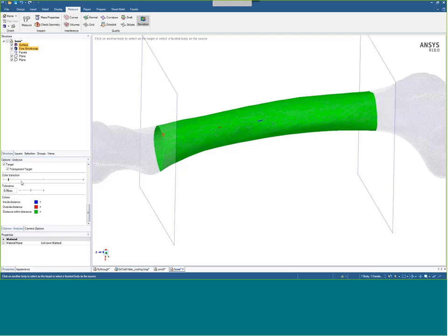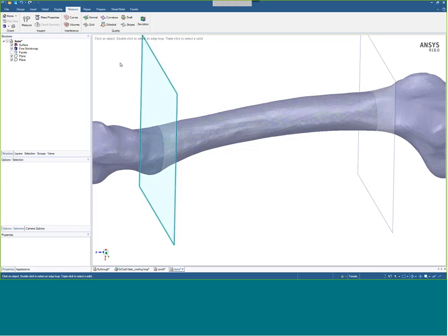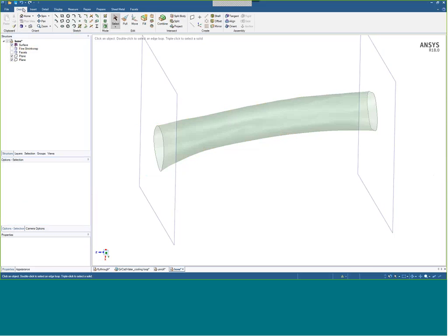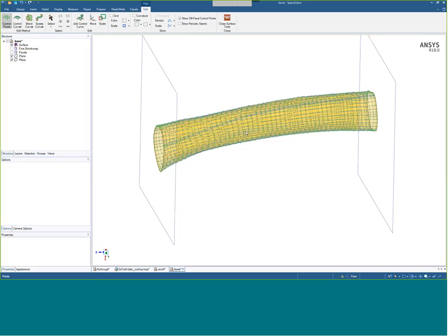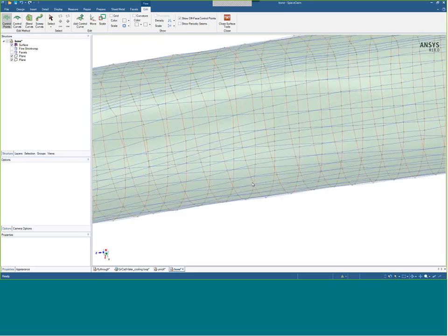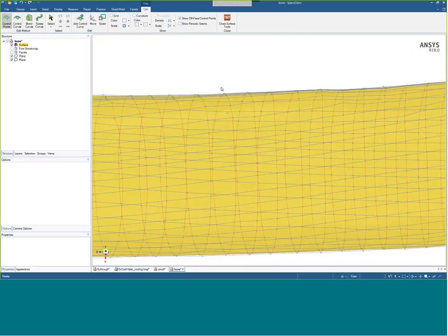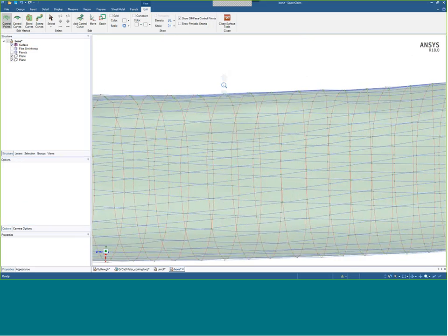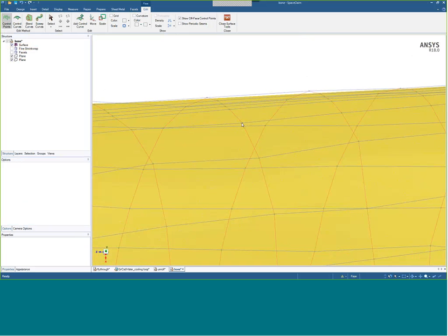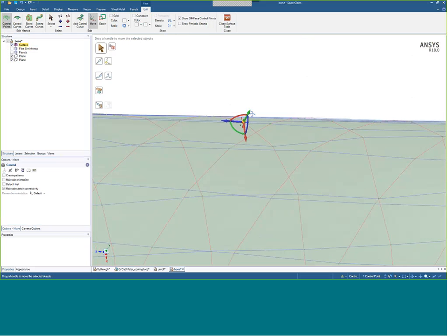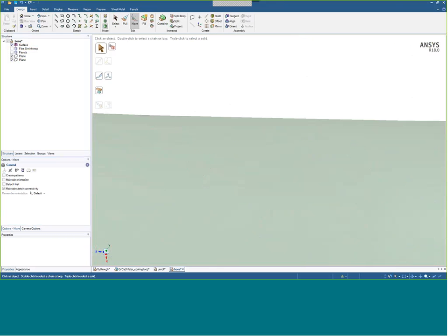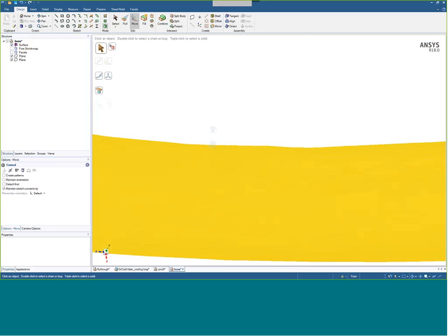And in the event that something is off or you might want to tweak something, you could go back in and literally control the tweak face, these curvature points on the surface. If you actually had a section that was off by a lot, you could tweak the location of any of these points or corners. But in reality, the skin surface works really well to create a new surface over the STL, and I rarely have to do any editing after I create a surface.